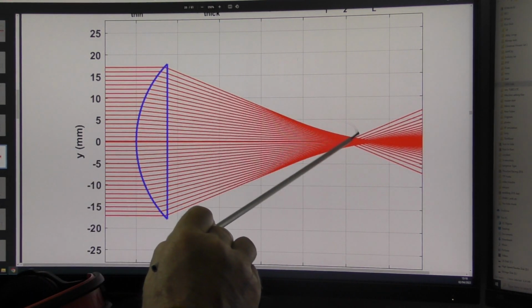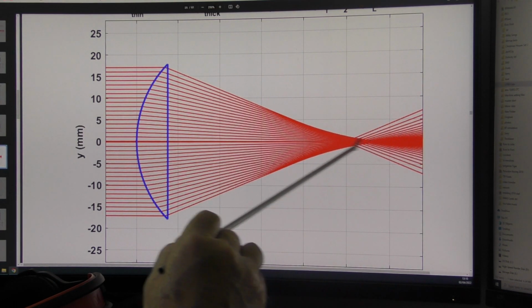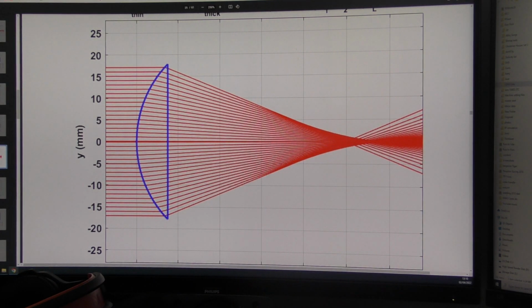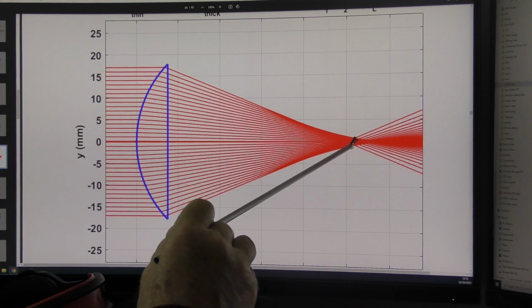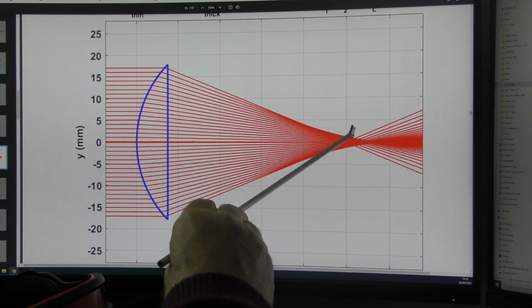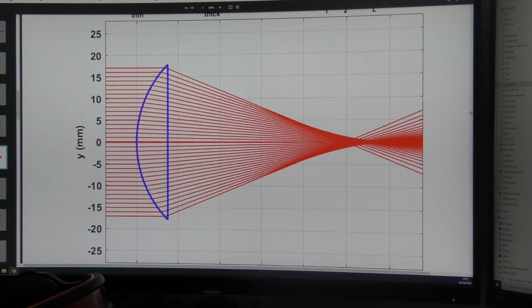Now let's take it right to the extreme here and say, let's forget about this aberration and assume that all these rays happen to coincide at this point here, which I'm going to say is 1 square millimetre. So I've got every one of these rays stacked on top of each other at this point. If this is only 1 millimetre square and I've compressed 100 watts into it, then I've now got 10,000 watts per square centimetre.